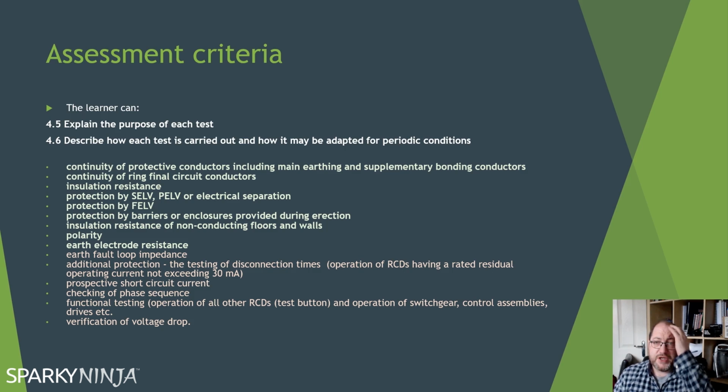On initial verification, yeah, you can buy stuff brand new that doesn't work, so you need to verify the functionality of everything. On a periodic inspection, you can just assess if things are suitable for use, and you can just verify it by the fact that people have been using it. You can ask if things don't work. If you have an area that isn't commonly occupied, you maybe want to functionally test some things yourself. Your isolating switches, for example, they should be functionally verified.